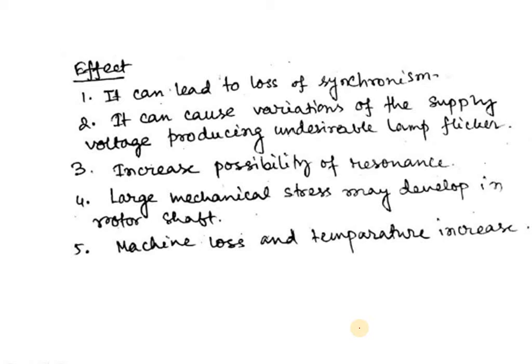Secondly, it can cause variations of the supply voltage, producing undesirable lamp flicker. Thirdly, increased possibility of resonance. Fourthly, large mechanical stress may be developed in the rotor shaft. Fifthly, machine loss and temperature increase.